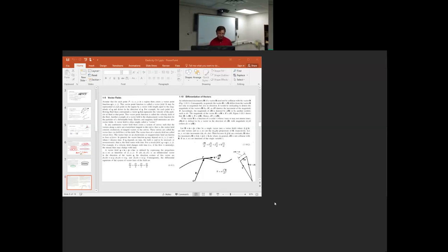This function again in space would be the vector in this case, because it will give us the so-called streamlines, which may have components u, v, and w. U, v, and w in elasticity would be displacements, and the path along which particles move for the displacements of a particular particle will be called streamlines. It could also be used for fluid flow, but we will always be coming back to elasticity of a solid.